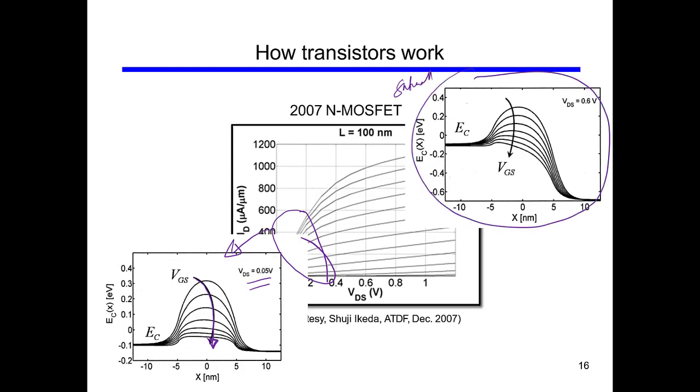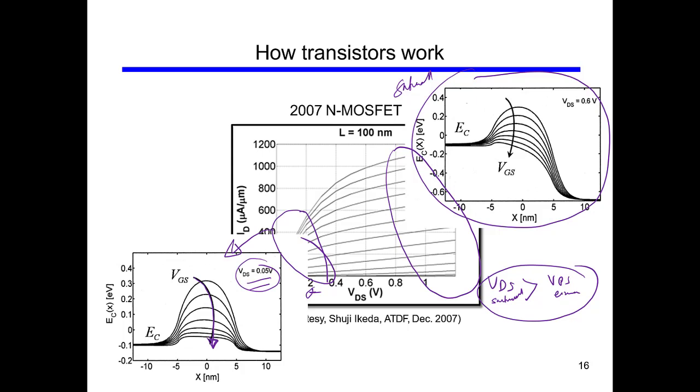In the saturation region, this is the situation. So where is the saturation region in this graph? It is here. You see here VDS is greater, so this is the saturation region. It is greater than VDS linear. The VDS linear is down here, it is very small. You see the value here, and the VDS saturated then starts somewhere here, so it is above here.